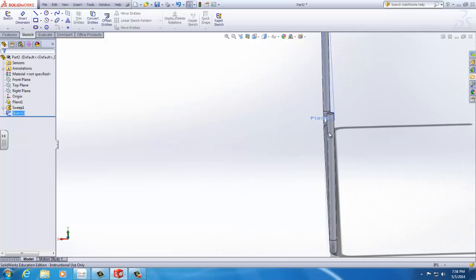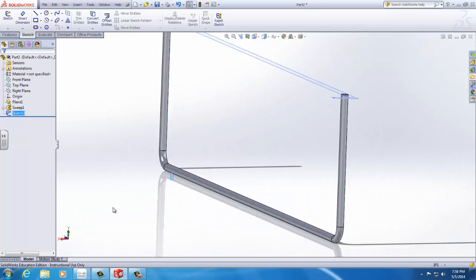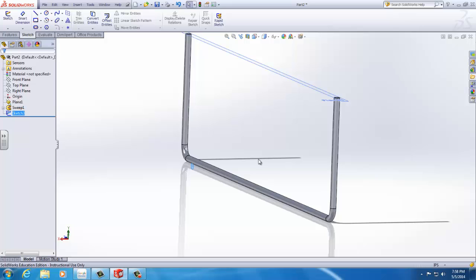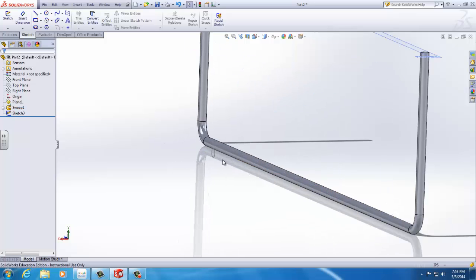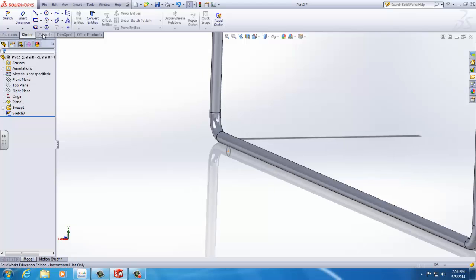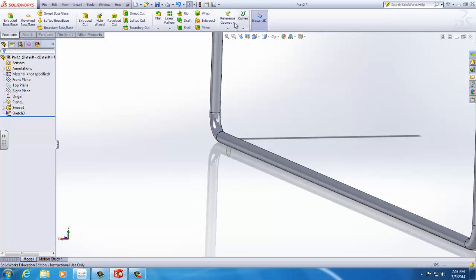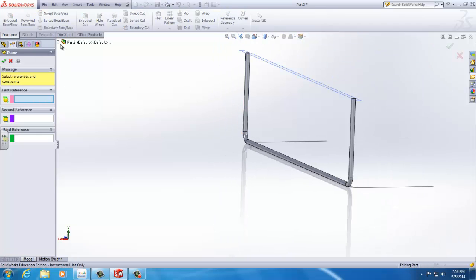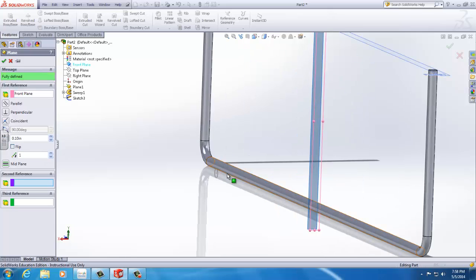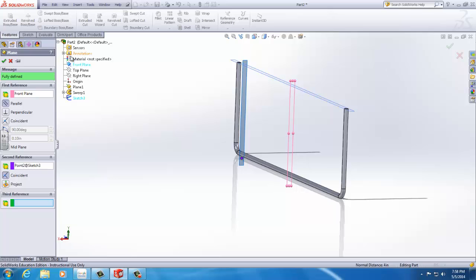Now the only thing that's going to be missing for the top circle is its path. Which we have to create. I'm going to create a sketch. To do that, we also need a plane for it. And we're going to do the same thing that we did before. We went to tools, features, and sketch plane. Pop up the same window, same location that you picked for the last plane, and in reference to the center point of the circle, we'll do the same thing again. It's going to create it in that plane.